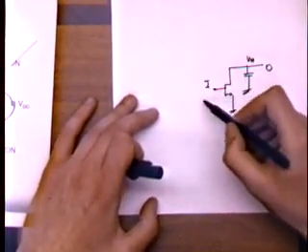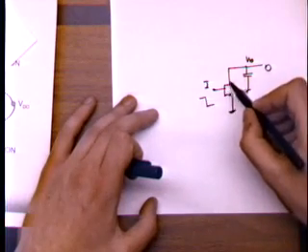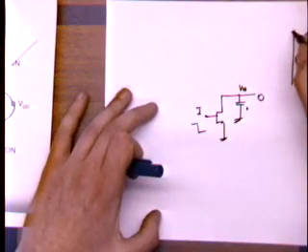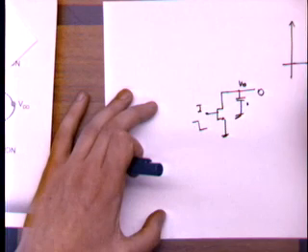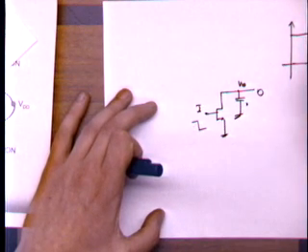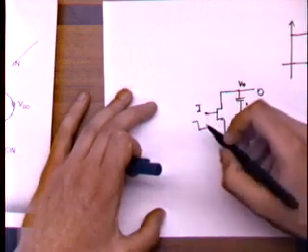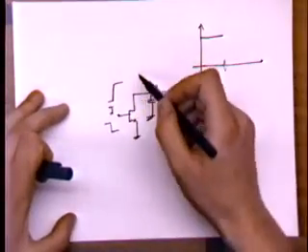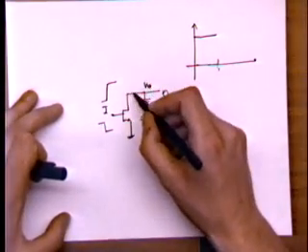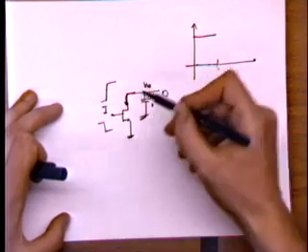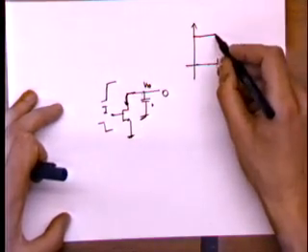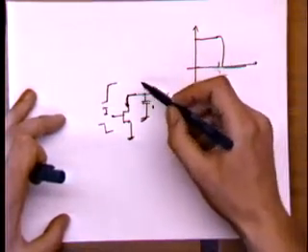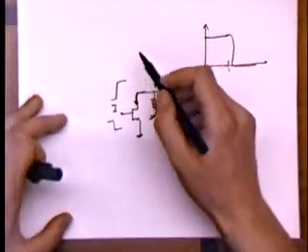So you can imagine when the input comes and it's low, this inverter doesn't draw any current, and the capacitor stays at VDD, right? So in terms of static characteristic, if my input is low, I'm going to get an output high, okay? But if I now pull the input high, this inverter is going to discharge the capacitor through its drain current, and the output voltage is going to go to 0, okay? So this is a valid logic gate. Of course, the fact that you precharge this capacitor means that you need another transistor to do it, okay?